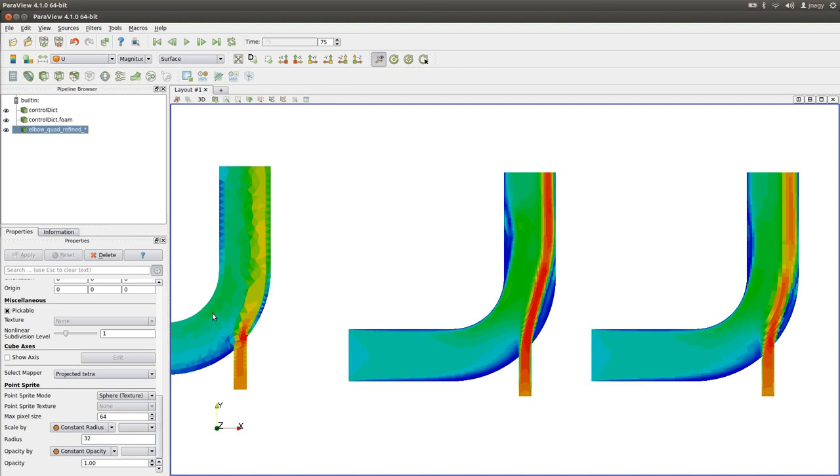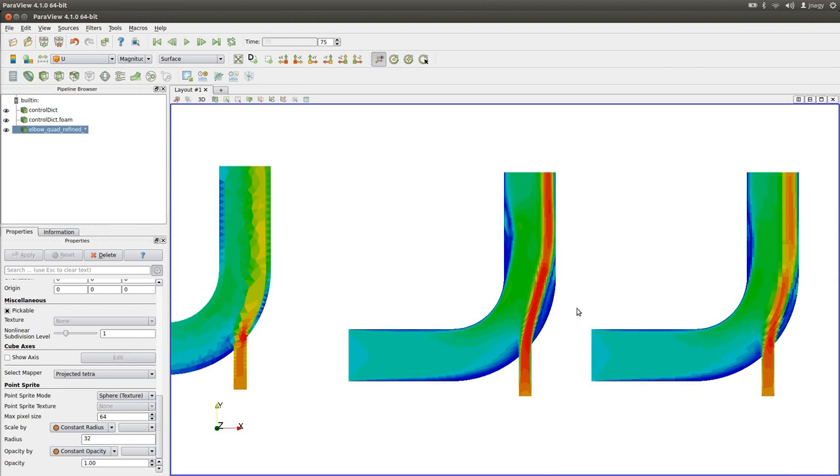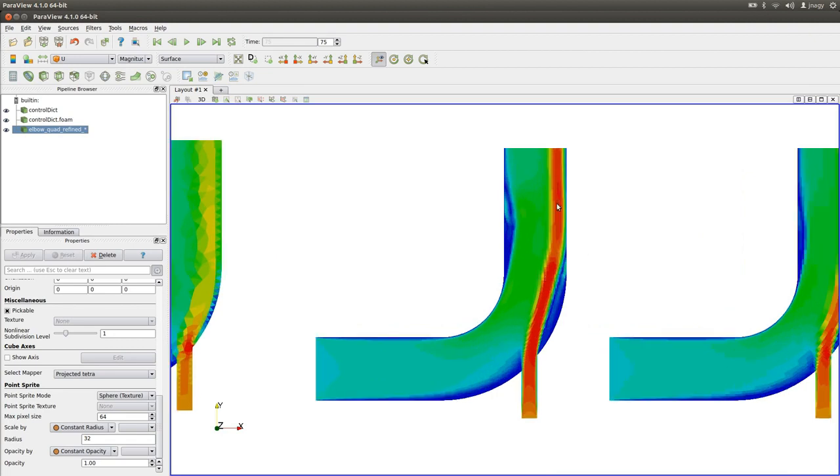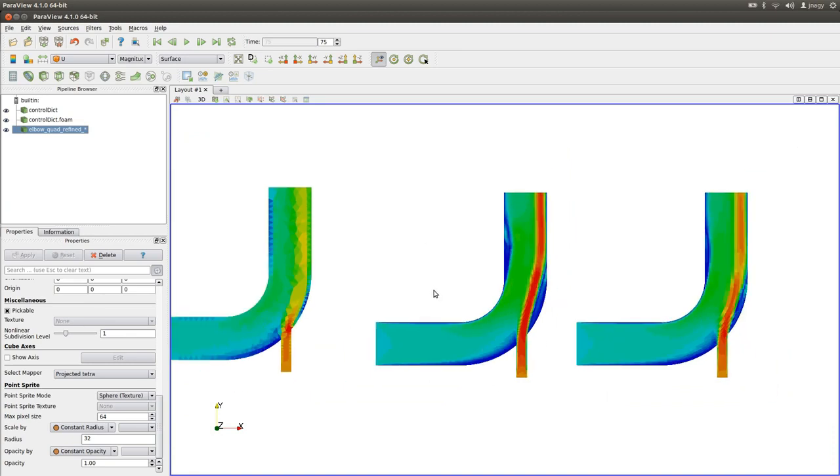So this is the reason why it is very important to think about your calculation grid and the quality of your mesh. Obviously, this mesh is not very good for that. In order to depict large scales, that the velocity is going here in the positive X direction and here in the positive Y direction, and then here something's happening, then this grid is good enough. But in order to depict details like this backflow or the velocity maximum here, then you really need a better mesh. This is the reason why I want to show you. And in a later tutorial we will come back to grid convergence, where I will show you exactly this phenomenon.